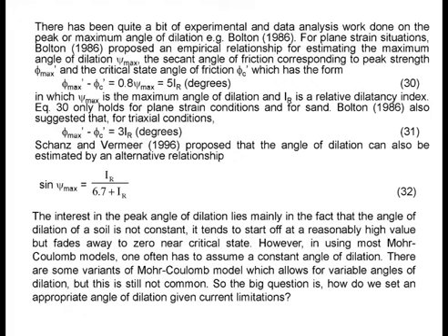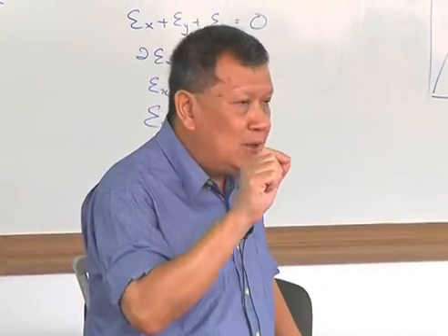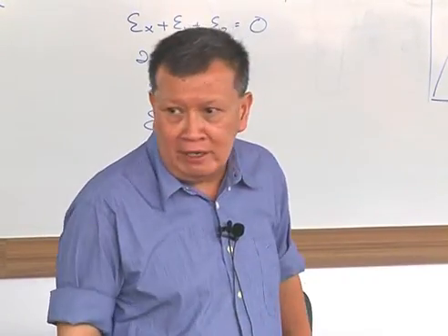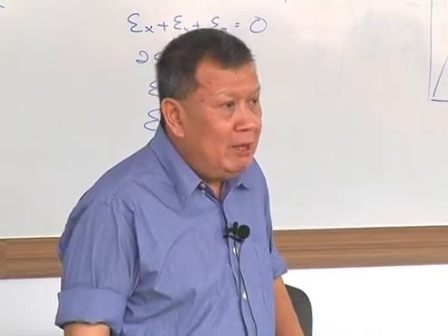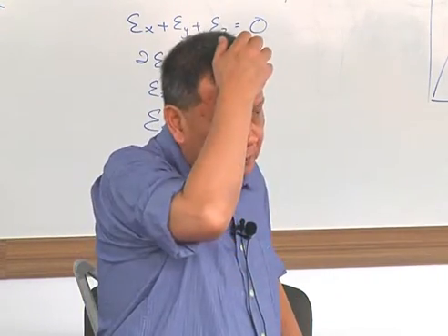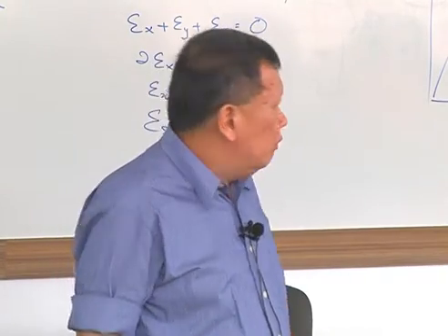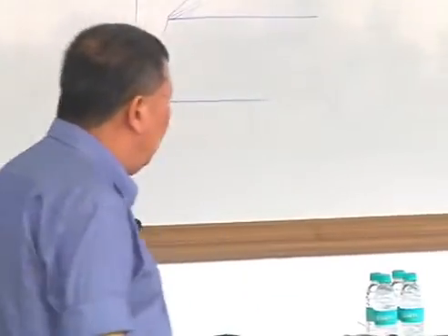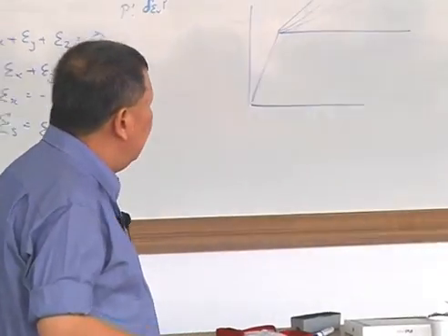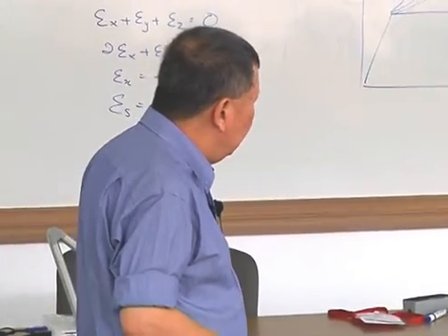All right, and there is some software. I think Abaqus is one of the software. I think GeoFEA is okay. GeoFEA will take zero angle of dilation, but Abaqus, for some reason, you've got to give it a very small positive angle of dilation, like 0.1 degree. Otherwise, that was a version of Abaqus I used, 6.7, otherwise it just goes unstable. Okay, so you have to explore the software a bit. Okay, right. I think that's basically it for the angle of dilation.